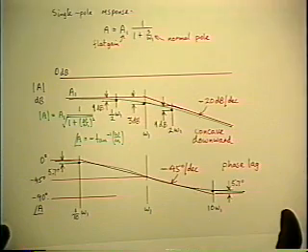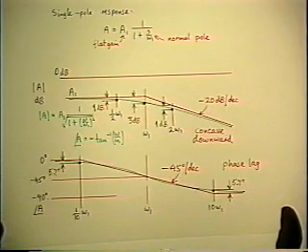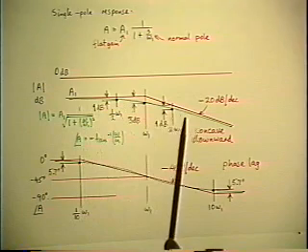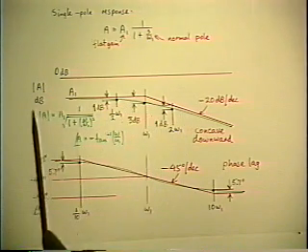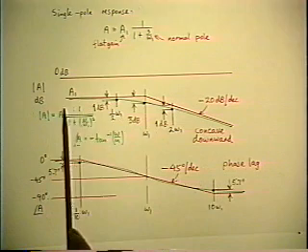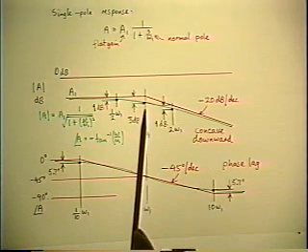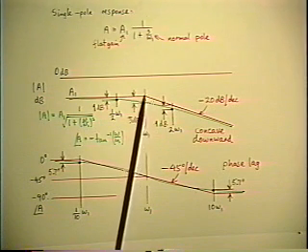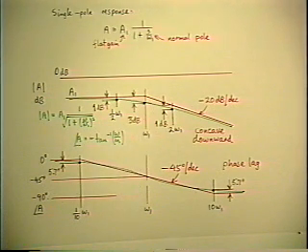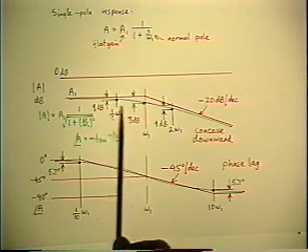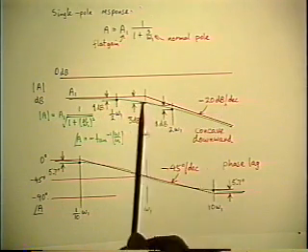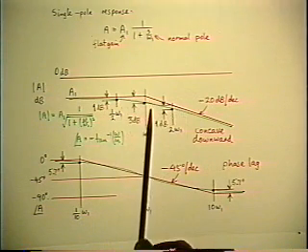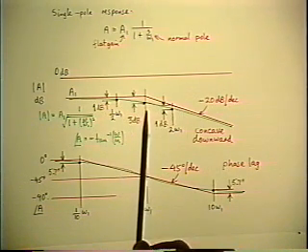Well, everyone knows that that's the 3 dB down point, and really all you have to remember about the asymptotes for a single pole function are that you have the sharp corner of the asymptotes, and the actual curve is 3 dB down at that point. There's a couple of other points that are useful to know about also, because the only thing that you don't know by using only the 3 dB down point is that you don't know what is the frequency scale involved. You don't know how far this gradual curve is extending on either side of the actual corner.